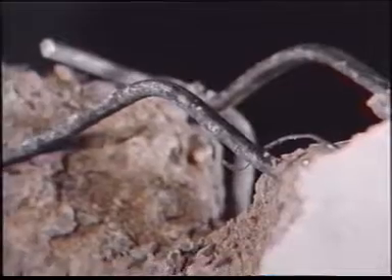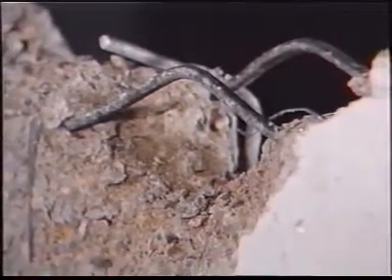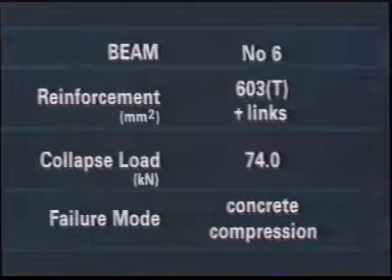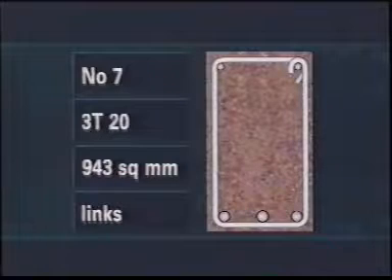When it is taken beyond failure, we can see how one of the links has been sheared by the considerable load applied, 74 kilonewtons. Again, the results show a pattern: greater reinforcement, less deflection, greater load.